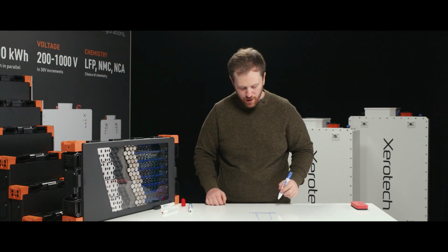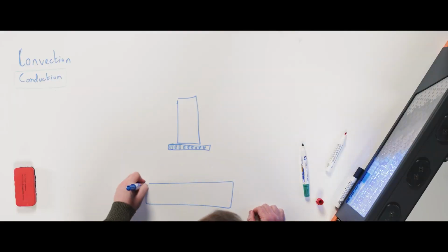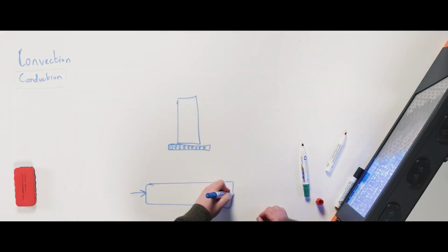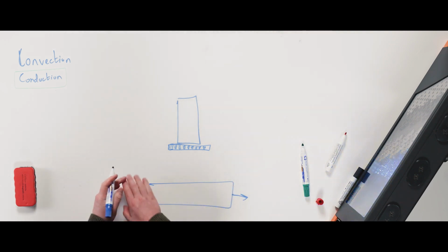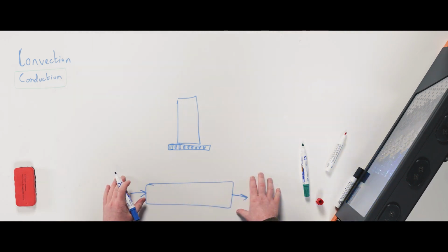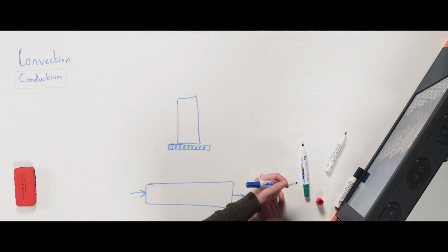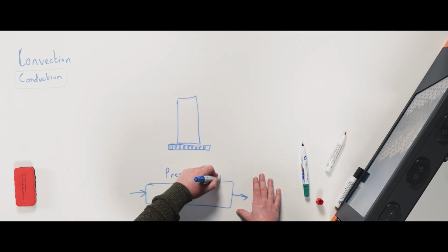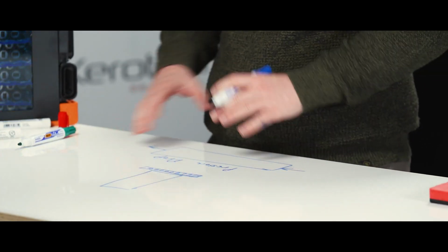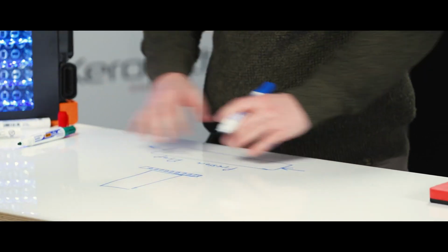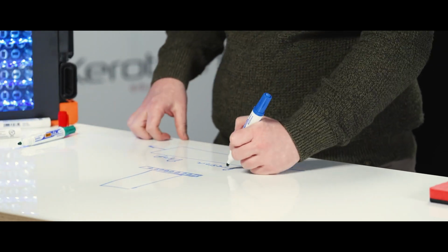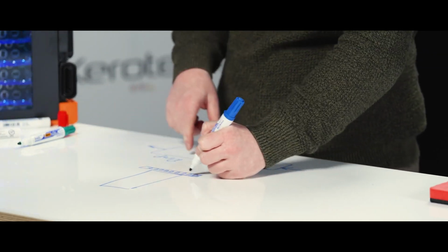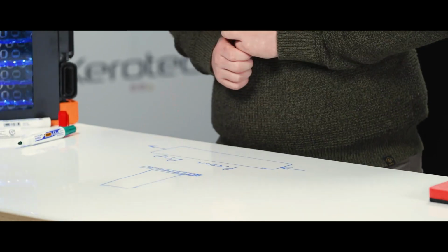And that means that as we flow through from one end of a pipe to another, I need it to be higher pressure on this side than here, because the water has to flow across it. And that means that you get something called pressure drop. You lose pressure, you lose energy. It takes power to pump water through something. But what's important is that that pressure drop equation is very non-linear.